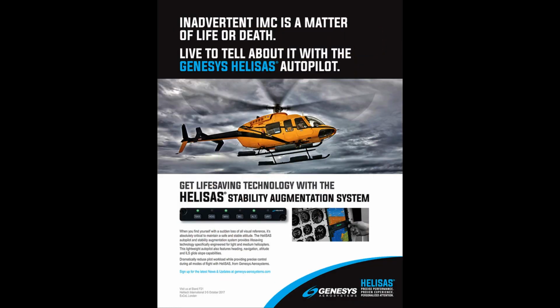Autopilot. Helicopter autopilot systems are similar to stability augmentation systems, but they have additional features. An autopilot can actually fly the helicopter and perform certain functions selected by the pilot. These functions depend on the type of autopilot and systems installed in the helicopter. The most common functions are altitude and heading hold. Some more advanced systems include a vertical speed or indicated airspeed, IAS, hold mode, where a constant rate of climb/descent or IAS is maintained by the autopilot.